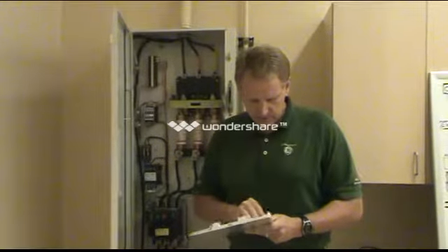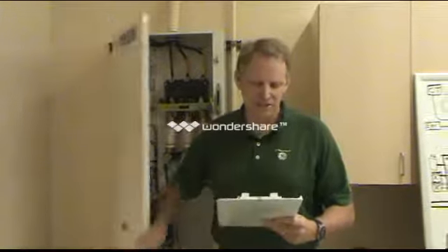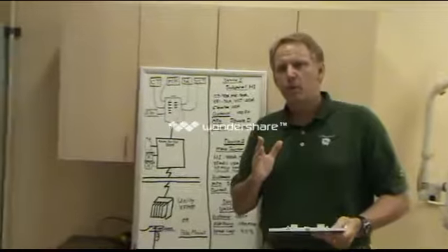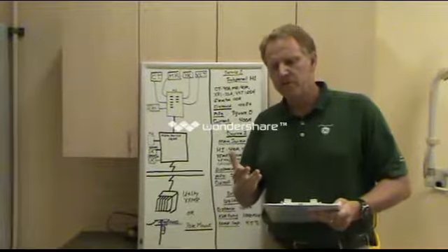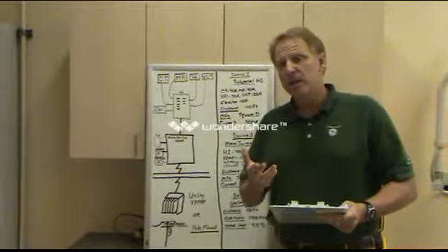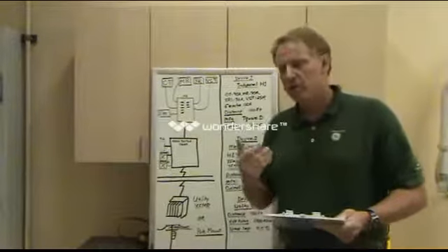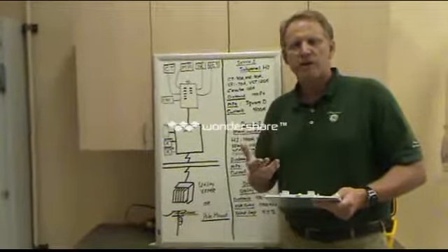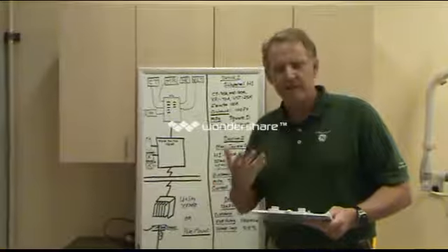All right, step 3, page 3, the most often ignored section. This is documenting the power path. Here's the intent: we are looking for loading, and we're looking for a transformer. If you use the analogy of a network system, the transformer acts like narrowing the bandwidth going to the equipment, like a choke. If not enough power is going to the equipment, you're going to have stress build up inside the equipment and eventually have problems with failures.